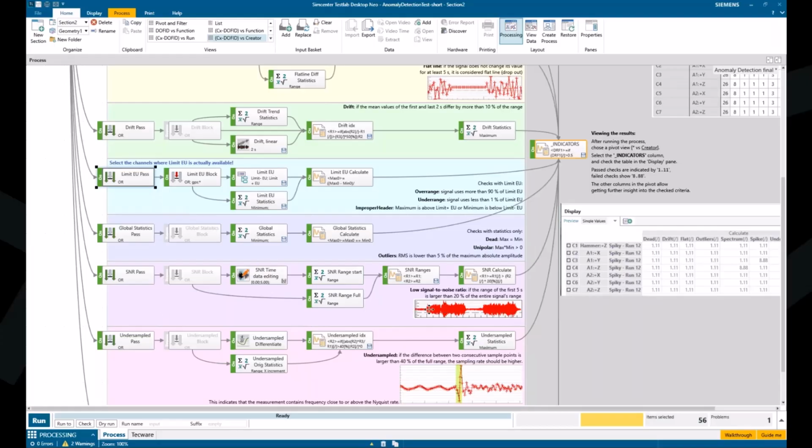So in the beginning, you have something which is, well, lower amplitudes, then you start the tests, and you have higher amplitudes. Maybe there was a pause in between, and then a second part of the test, and then it finishes. If you have a signal like this, it makes sense to check the range in the first part compared to the range of the full signal, because that is the comparison between the measurement when the component was idling with the range of the measurement when the component was under stress, under test.